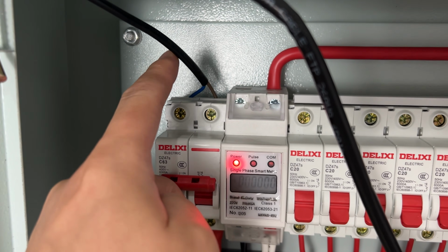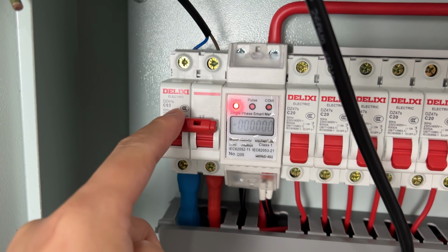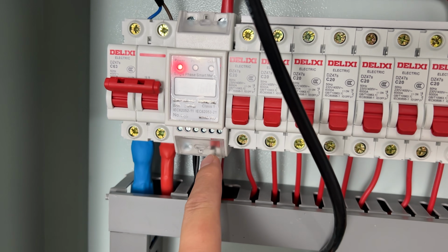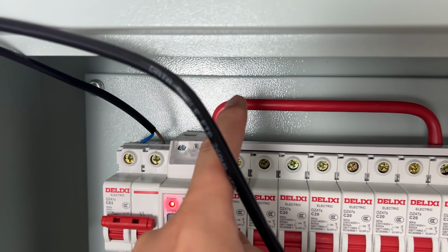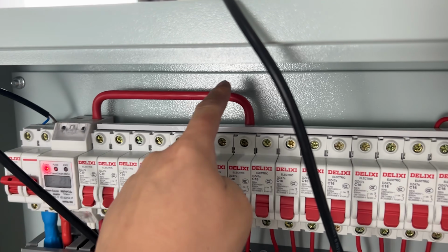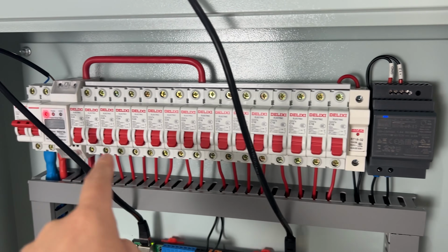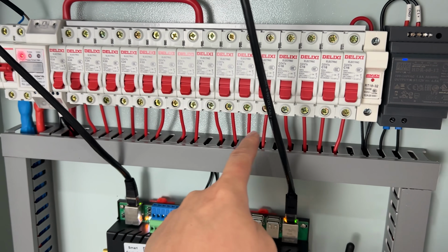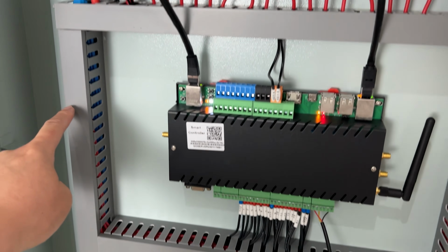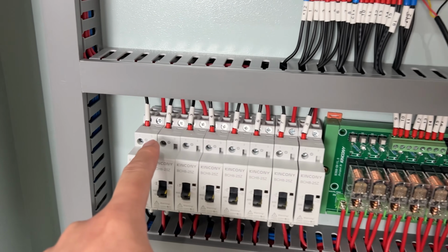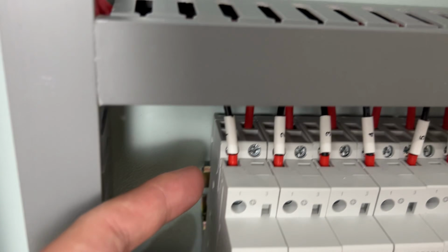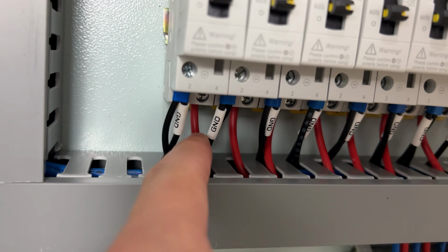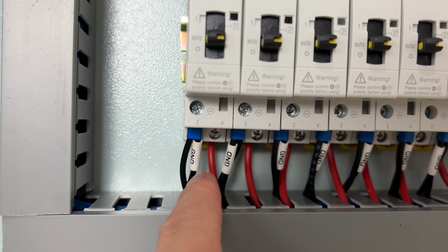You can see this is the AC power in, and this main breaker, and this power goes to this energy meter, and the energy meter will output here for the 16 channel, this 16 channel brick. And this brick output, you can see the red output will go through this way and to this contactor. This is the power input, and this is the output. So you can see the red is output.